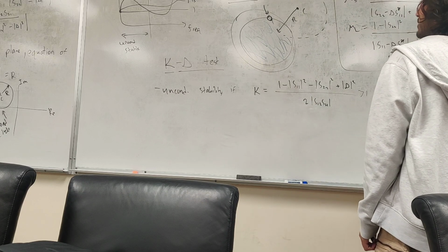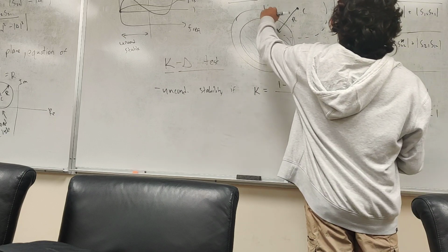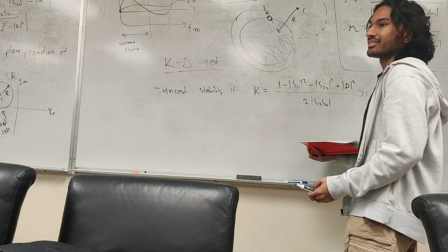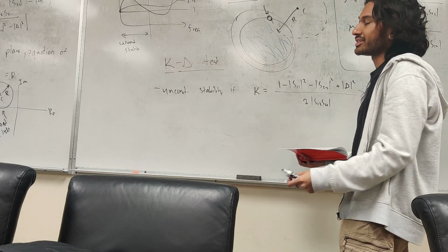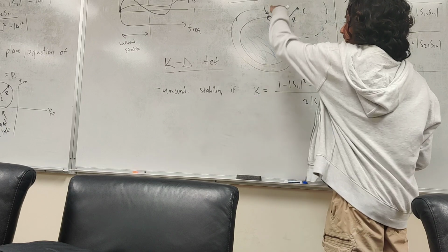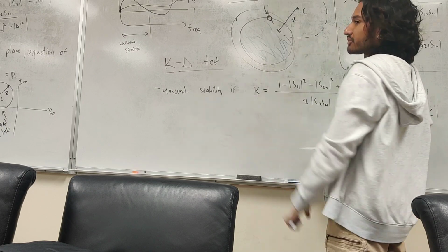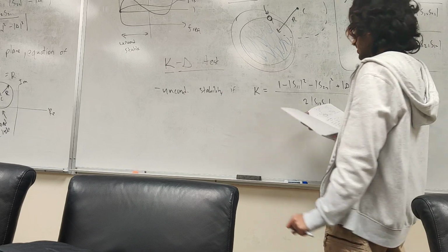We say, okay, we want to go in here. In the Smith chart, as you go further out, our impedance gets higher, because we normalized to 50. So 1's over here. If we want to go this way, we want to bring our impedance down from 200. So what do we do?